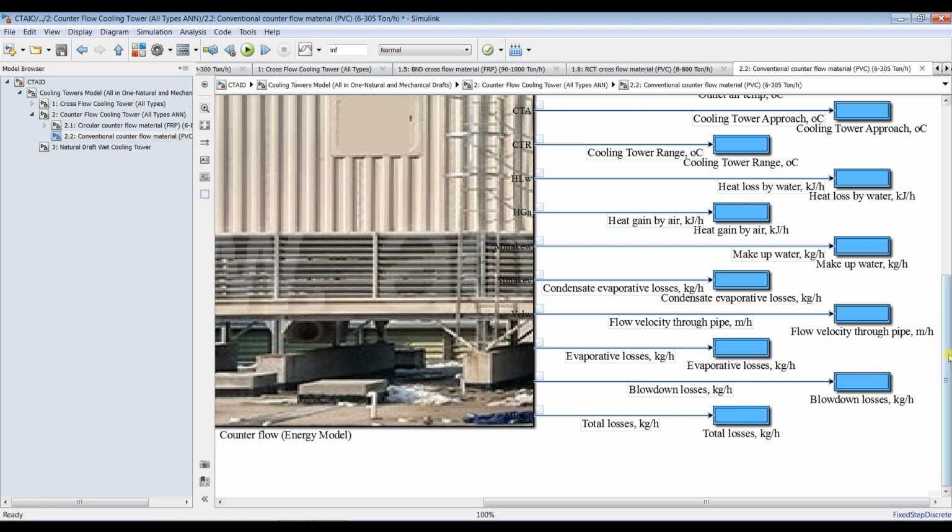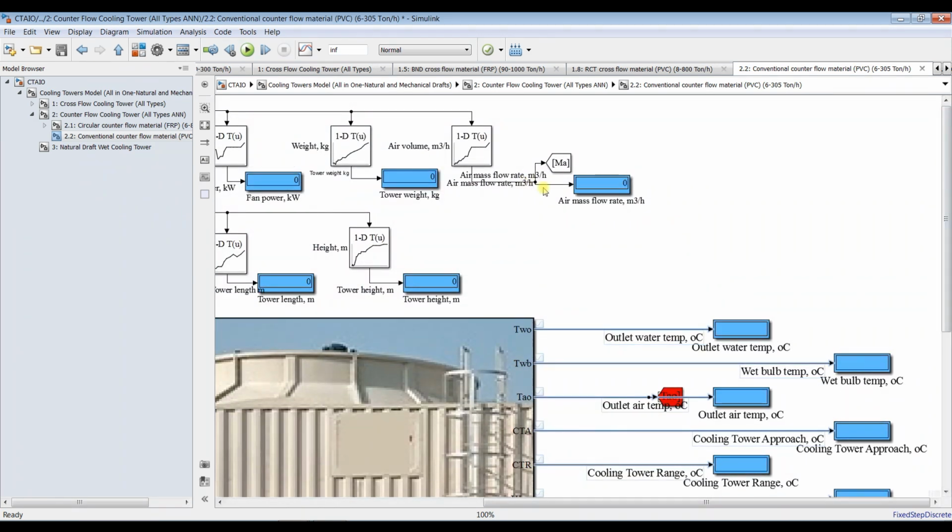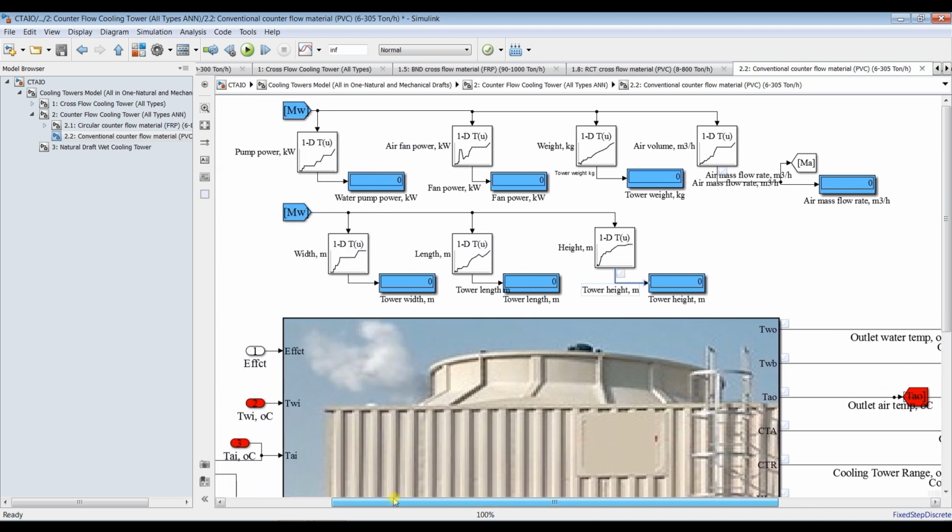Okay, and for this one we have to double click here and click signals, in order to realize the output on data inspector. Just a few parameters in order to compare between two different models and so on.